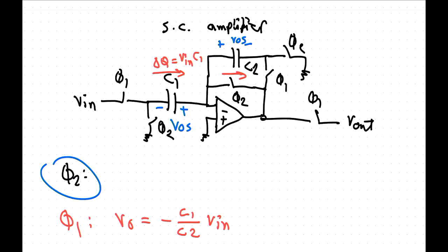A relatively new circuit there is the time-to-digital converter, which is like an AD converter in the time domain. You look at two time differences and turn that into a digital number, and you use that in a PLL.